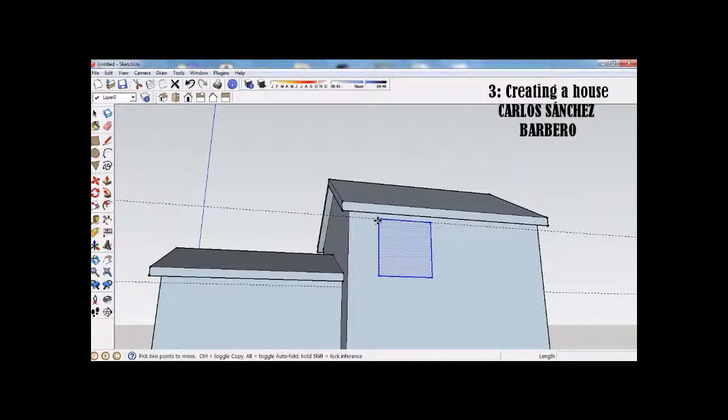Triple click and move it. Using the select tool, select the window to be copied. Select the move tool and press and release the Ctrl key. The cursor will change to a four-way arrow with a plus sign. Click and select the window to copy. Move the cursor and click at the destination point to finish your copy operation.